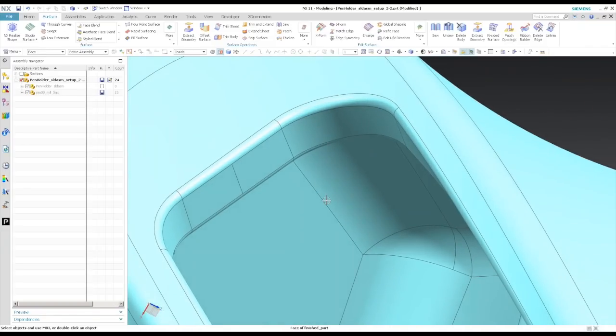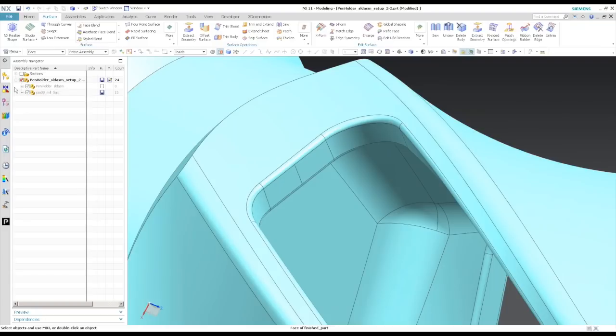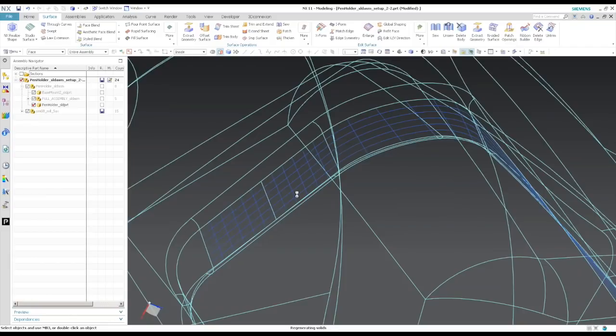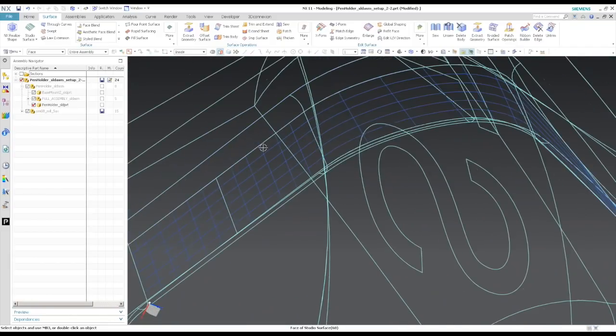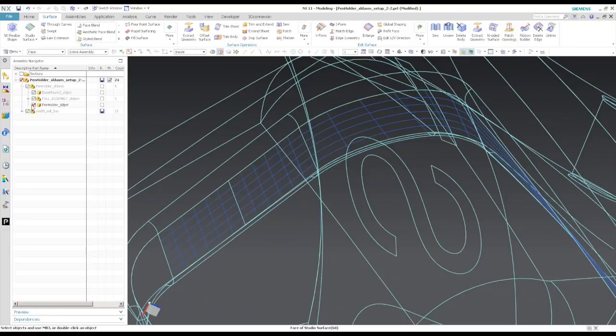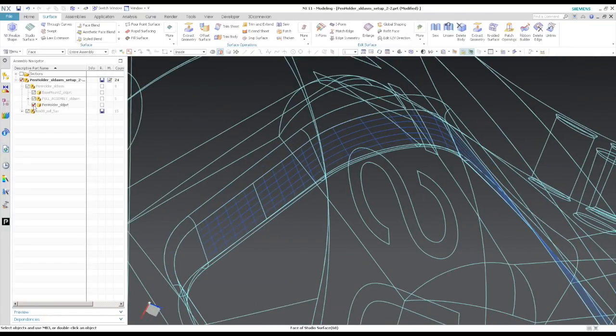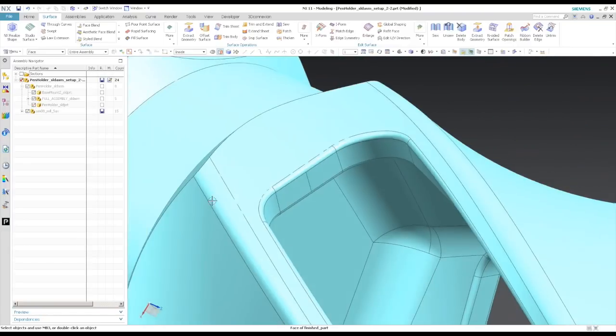And the way that NX assemblies work in CAM, we're not even affecting the engineered part that was sent to us. We haven't touched it. We haven't resaved it. This is an associative copy for manufacturing. It'll update. Even if we do modifications like this, we can do analysis to compare it to the original part, so we can overlay faces and look at, like we are here, two of the parts overlaying as far as the untouched engineering model versus the optimized manufacturing model.